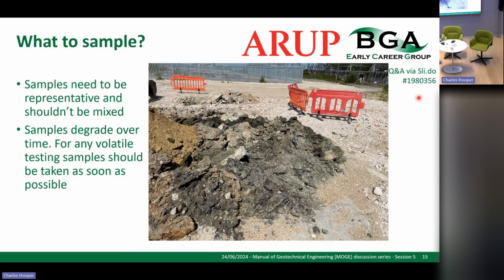If you were to take these and compare them to fresh samples, it could be orders of magnitude difference in the concentrations that the lab would report. And there'd be no way of knowing, other than the engineer's knowledge, what the difference was between those samples. If you put them in the cool box, the lab will no longer be able to tell you. You might be able to work it out from the moisture content, and that sort of forensic testing does happen and can catch people out, where effectively this could be the difference between the material passing an assessment or failing the assessment for how much hydrocarbons are being recorded.